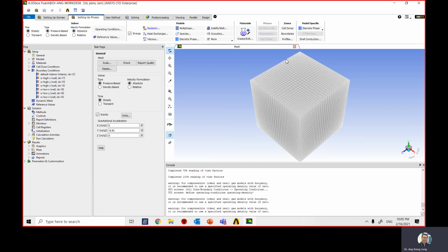At the back there is wall low X. So we have low and high. Same with the other faces. For example, y. The face that I'm selecting here is wall y direction high, and then the ground there is W Y low, and then this face is W Z high, and this one is W Z low. So this is how you identify the 6 surfaces here.